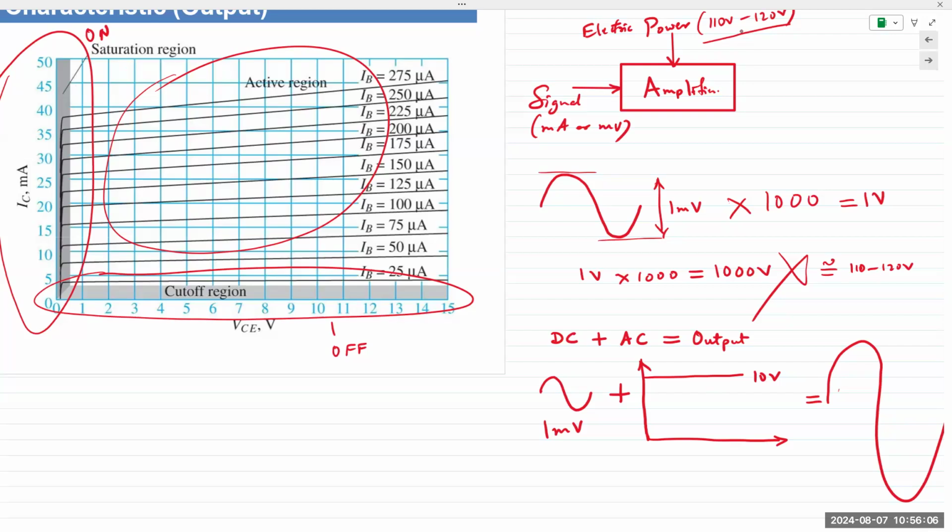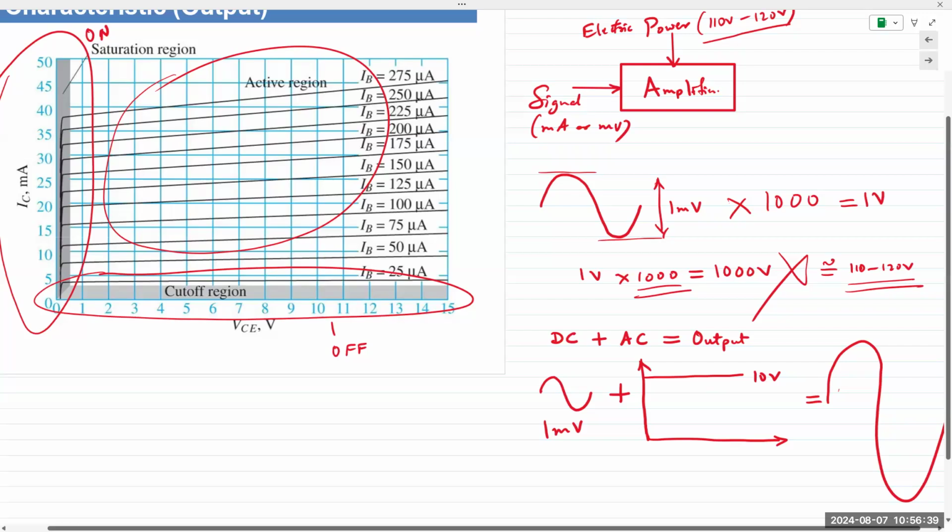So even if the amplification factor is 1,000, we are not going to get 1,000. The transistor is going to saturate at the level of the supply that we're connecting to it. If that power supply is 10 volts or 12 volts, the maximum you would obtain is 10 volts or 12 volts. It saturates at the level of the power supply, right? Otherwise, we could solve the world's energy problem right there, if somebody could figure that out. We'd just create power supply amplifiers and power everything. But that's not the way it works.